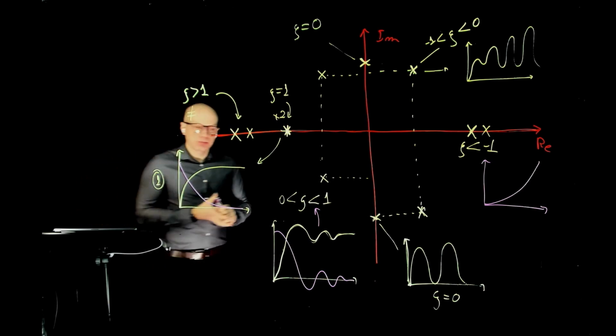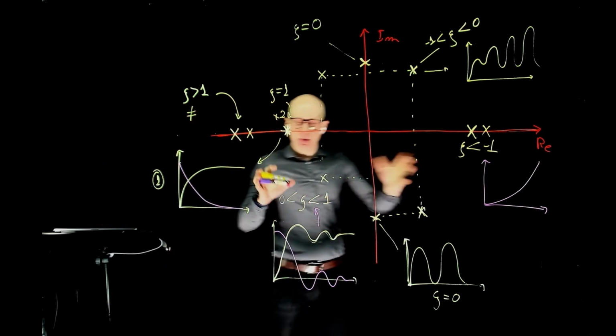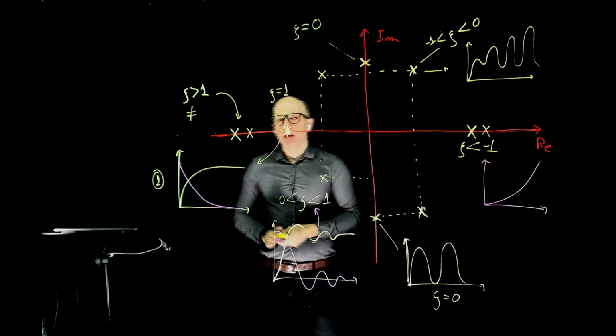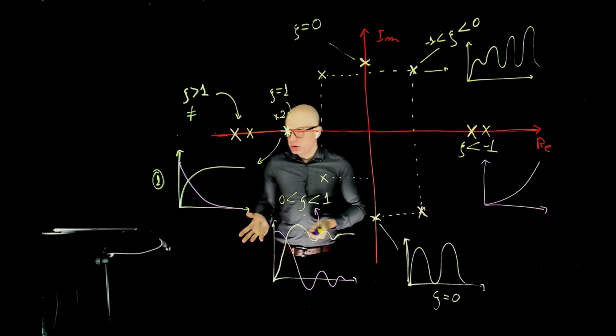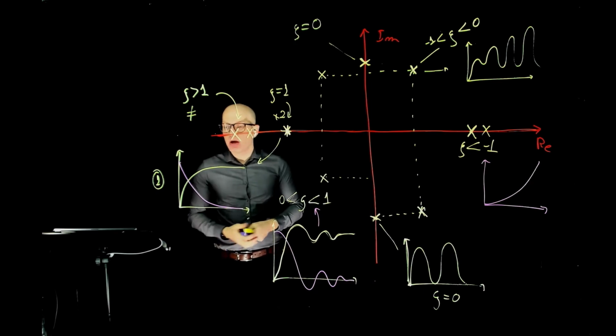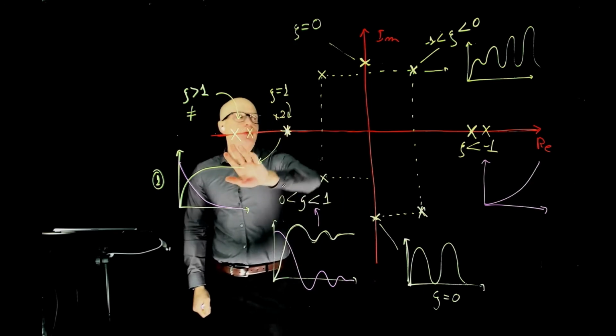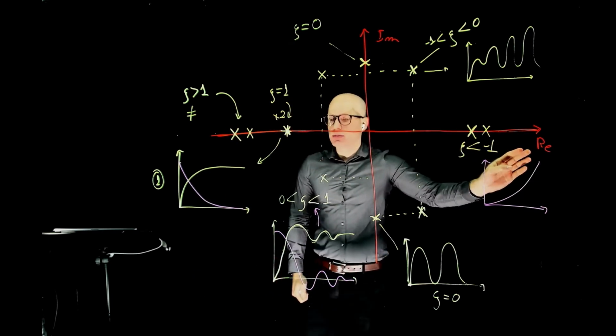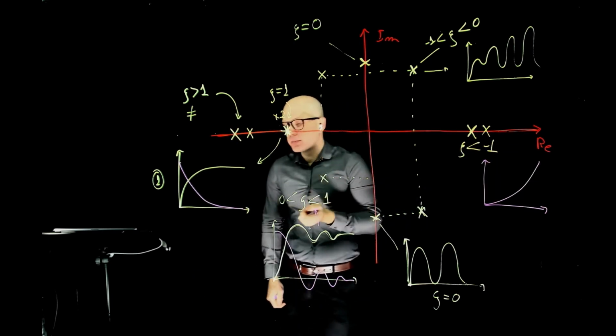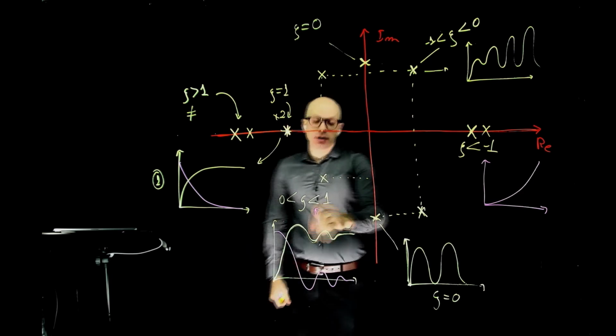Okay, so this is the entire picture of the system now. As we change, in the case of the mass spring damper system, the only parameter we would have to change to move from a completely underdamped system to a fully unstable system is the friction coefficient B, that directly affects the damping ratio.